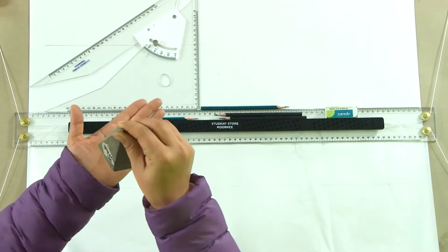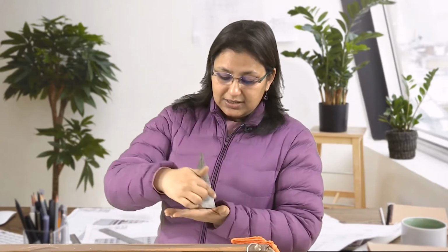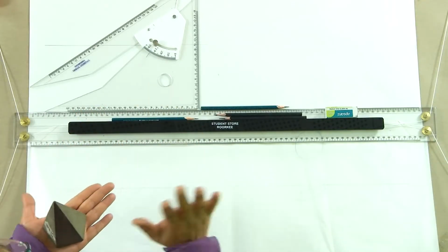So, if we look at this, let's assume it to be a square pyramid. Now, this square pyramid is kept in such a manner that its axis is perpendicular to the HP. This is the horizontal plane and this is perpendicular, and this axis which is vertical is parallel to the VP. So, we have this axis parallel to VP, a very simple position. The only thing is that the side of the base makes an angle of 45 degrees with VP. That is what we are going to draw.